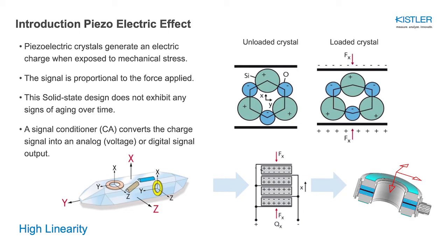Upon mechanical force loading, the piezoelectric crystal generates an electric charge response in picocoulombs that is directly proportional to the applied force. Due to the extremely high rigidity of the crystal, the overall deflection is extremely low, and as a result, the force sensor is very linear. This high linearity extends across the sensor's measuring range, which spans several orders of magnitude.